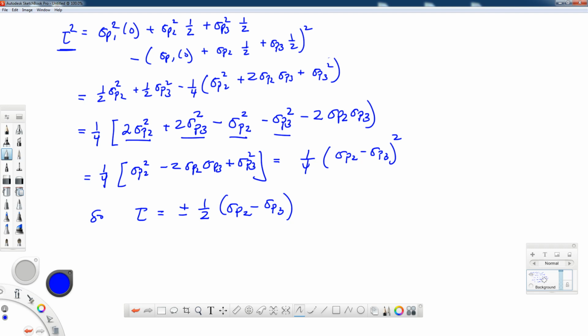So in this case, we're looking at between the 2 and the 3 directions. 45 degrees in between the 2 and the 3 principal stress directions is going to be an extreme value of local maximum shearing stress. The value of local maximum shearing stress is going to be 1/2 of the difference between those principal stresses.